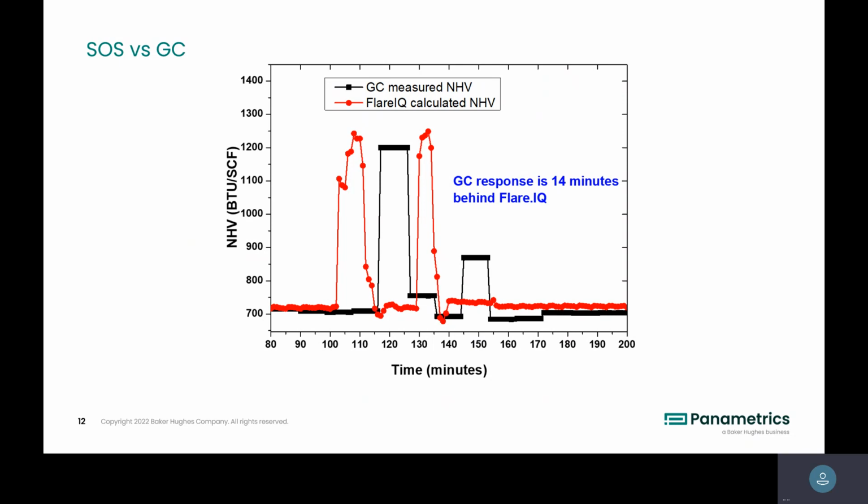And that's our patent for almost 20 years now. An ultrasonic flow meter measures the volumetric flow. But how do you get mass flow from volumetric flow? You need the density of the gas. Density is basically molecular weight; mass and molecular weight are just different terms for density for gas.